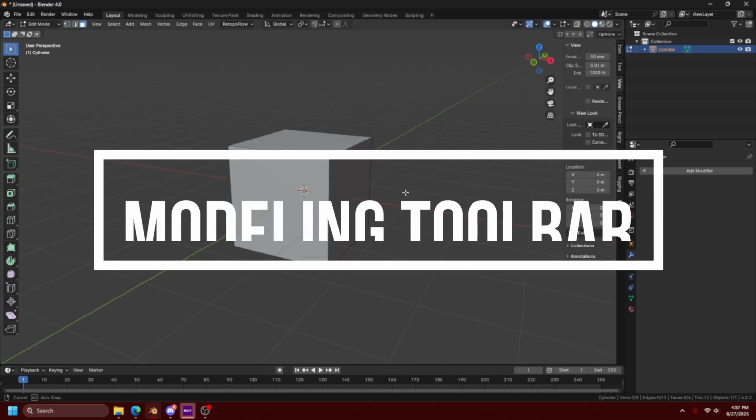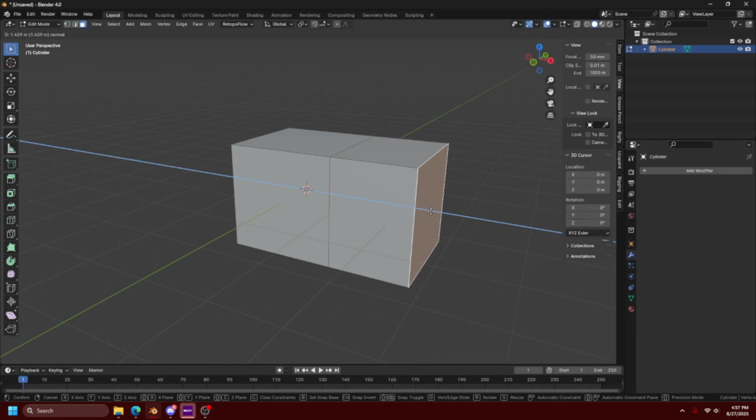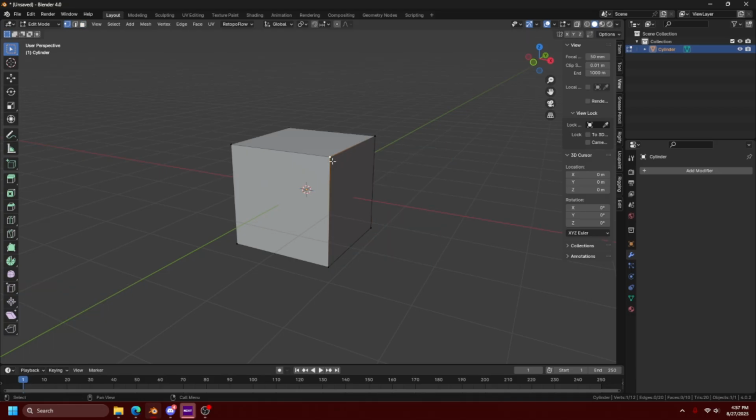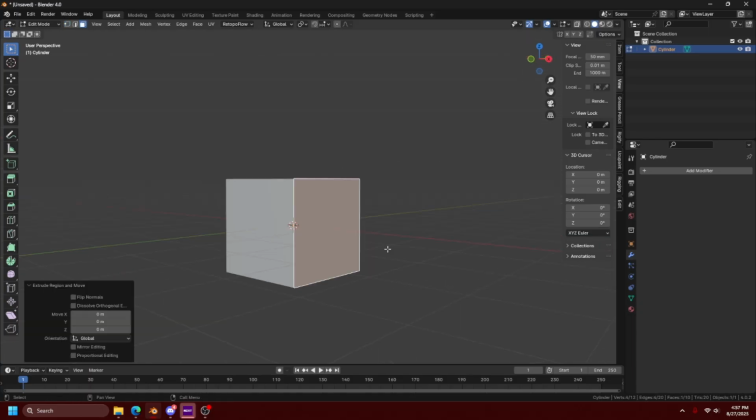Okay, first up is extrude. So you press E and you can extrude. Extrude does two things at once. It's a 2-in-1. So it duplicates geometry and then it moves it. Unlike every other tool, when you right click and extrude, which usually cancels everything, it looks like it cancels, but it's not canceled. So if you go into vertex mode and you move this, there's actually two faces on top of each other. Now, if you don't know, then it's annoying because you have all this duplicate geometry and you don't know where it came from.